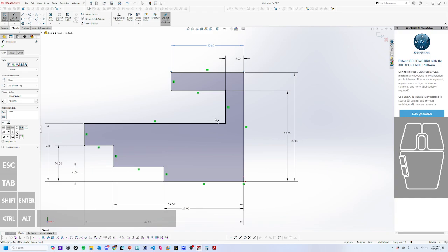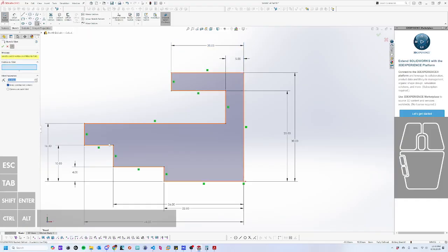All that's left is the fillets. So, actually, relatively easy. So, I'm going to put in the fillet dimension first. So you can kind of see right now the fillets are too large. So if I click this point, it says this fillet cannot be added because the specified radius would eliminate one of the elements. So I can see from the drawing that it's a 1.5 millimeter radius.